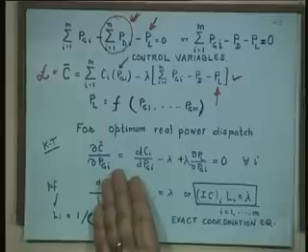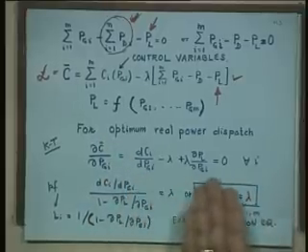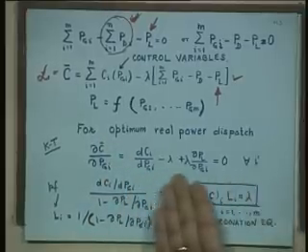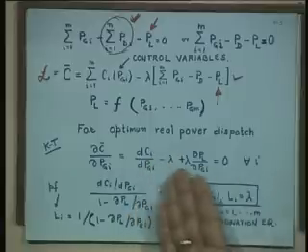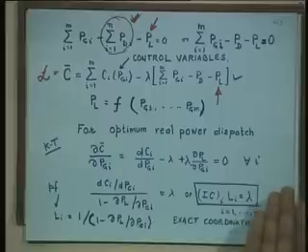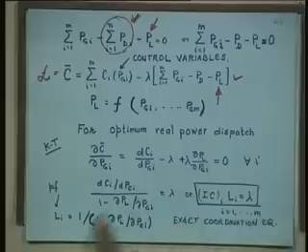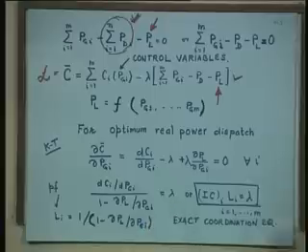Here is the only one control variable, so I differentiate it. Any BSc student, or even a high school student, will find this derivation: dCi/dPGi minus lambda plus lambda times ∂PL/∂PGi is equal to 0, for all i. You simplify, you get this equation: dCi/dPGi times (1 minus ∂PL/∂PGi) is equal to lambda.